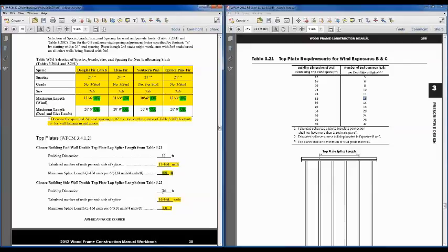The 40-foot dimension is going to require a few more nails per that table, so that's going to require 16 nails, and we're going to need about 4 feet of splice length to get those 4 nails in. So that's real quick. Again, there are a lot of calculations behind this table, but you can see how easy it is and time saving.